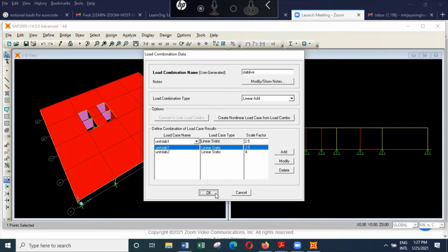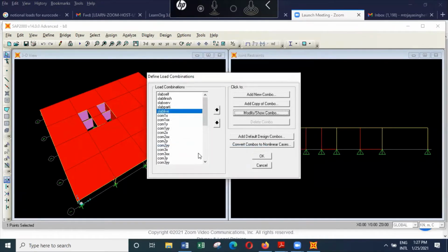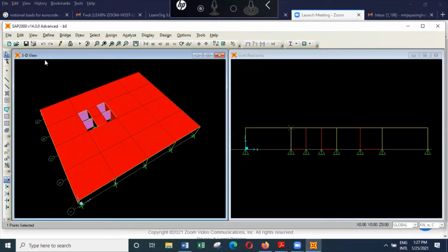Now we have got all these loads applied, and then there's another parameter that we have to think about. These are the loads, but how about the mass of the structure? Can some of these permanent loads increase the mass of the structure? So say for example, when you have a cement rendering, it's everywhere, so its mass should be represented. So what we can do is, we can go here.